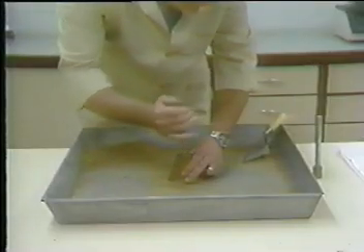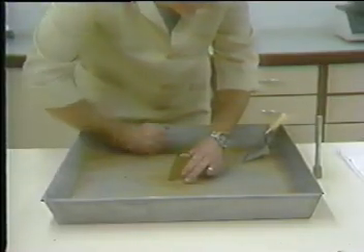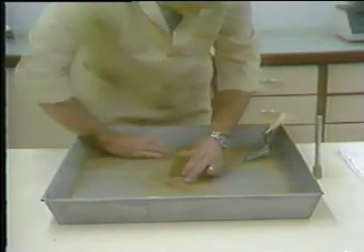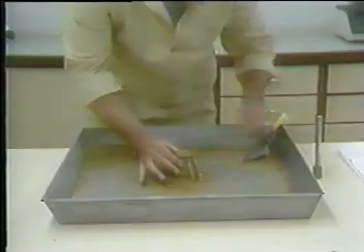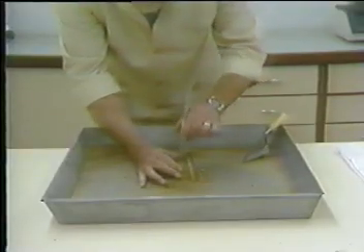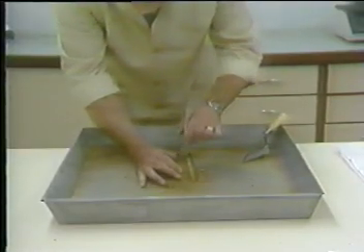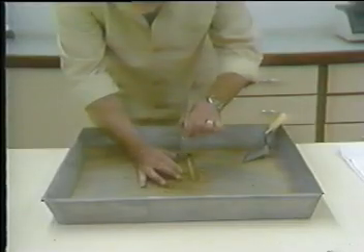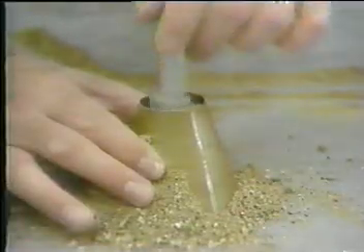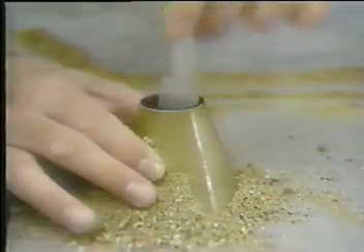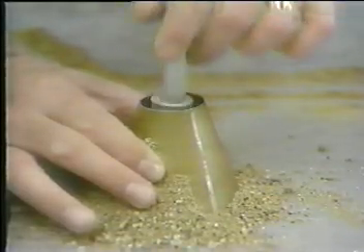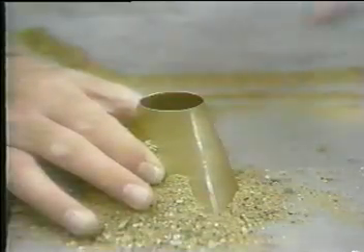Heap additional material above the top of the mold by holding it with the cupped fingers of the hand holding the mold. Lightly tamp the fine aggregate into the mold with 25 drops of the tamper. Each drop should start about 5 millimeters above the top surface of the fine aggregate. Let the tamper fall freely on each drop. Adjust the starting height to the new surface elevation after each drop and distribute the drops over the surface.